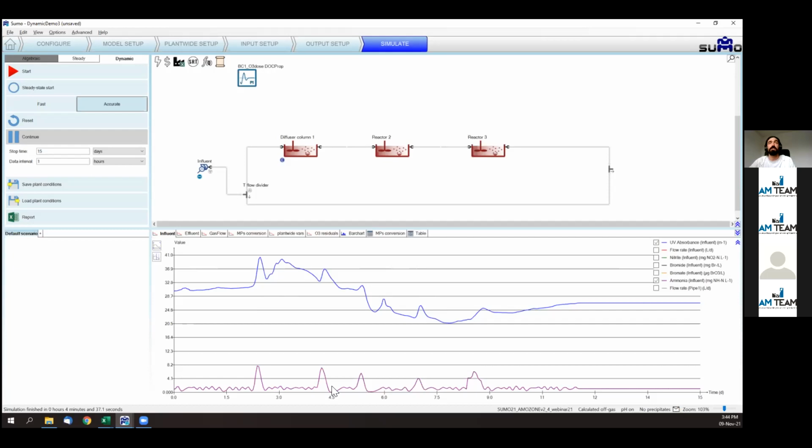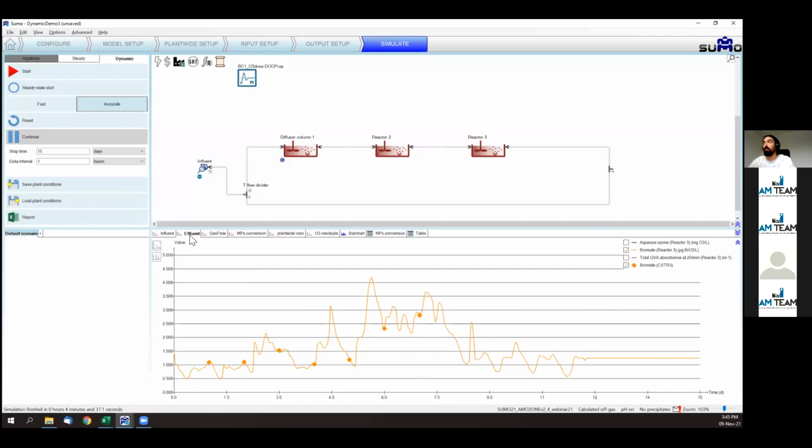There is an initial washout of the sewer, but then there is also a dilution effect brought by the rain event. And then also the operational settings of the upstream biological plant, which is over aerating and removing more ammonia than necessary, which is resulting in these peaks.